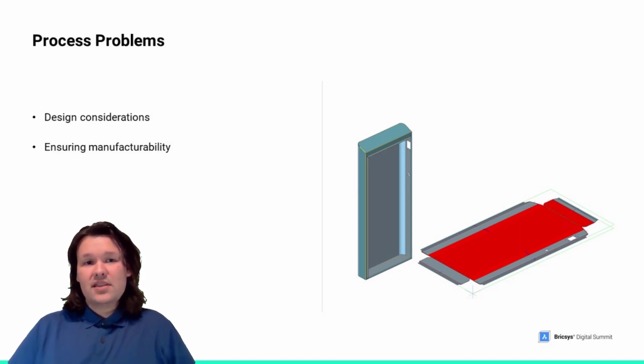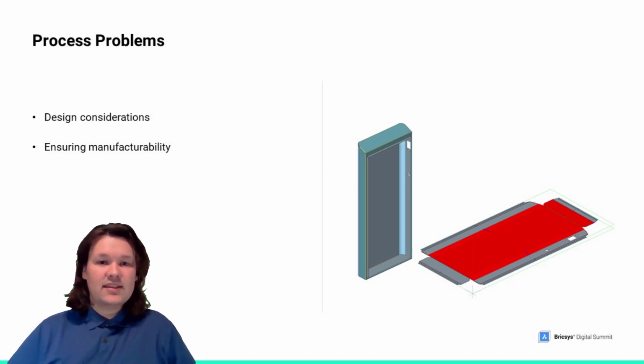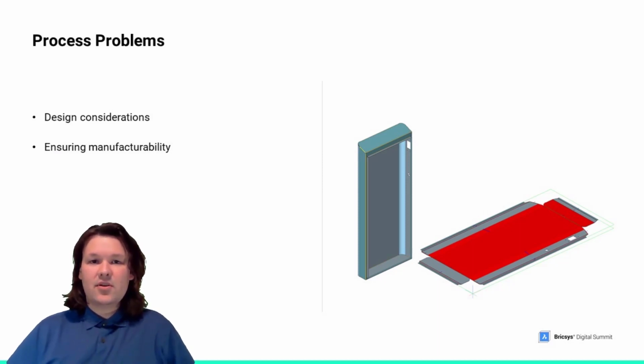Some of these considerations can be the wall thickness of the parts, that they contain a consistent wall thickness throughout the parts. The bend radius also is reflected and in relation to the thickness of the walls accurate. The K factor also is a consideration to have and an input to give accurate unfoldings. Certain things such as bend reliefs, which essentially are small details necessary for making the part manufacturable in an effective way, need to be modeled as well.